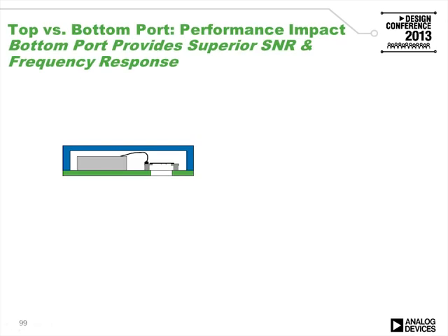One thing to note is that all of Analog Devices' MEMS microphones to date have a bottom port configuration, which means that the hole that lets sound into the microphone is on the bottom of the microphone and needs to be mated with a hole in the PCB when the microphone is soldered into a system.